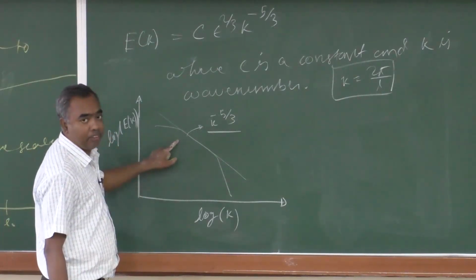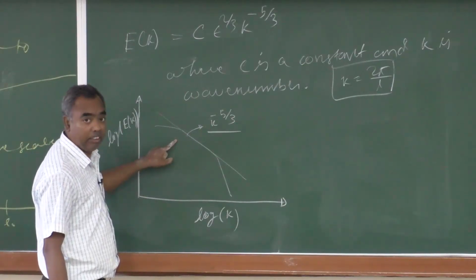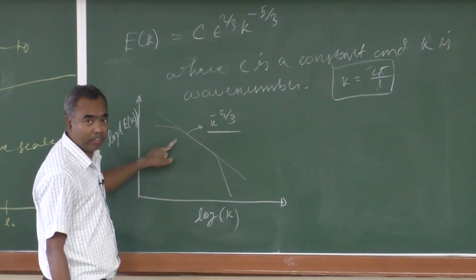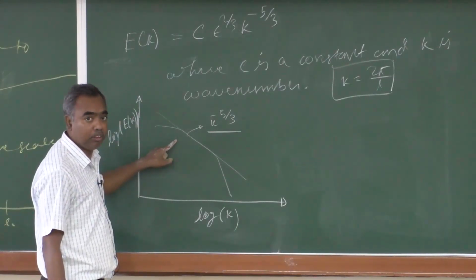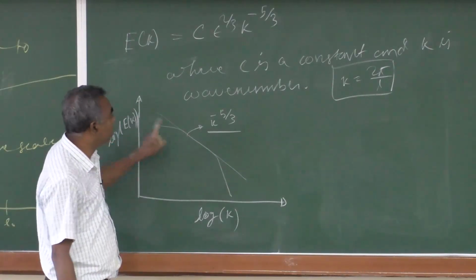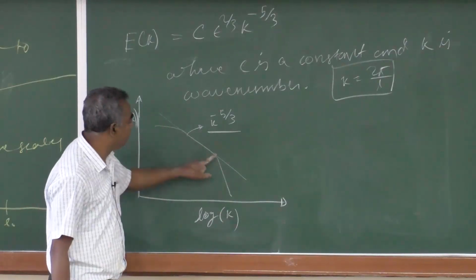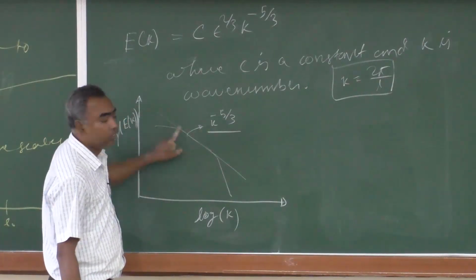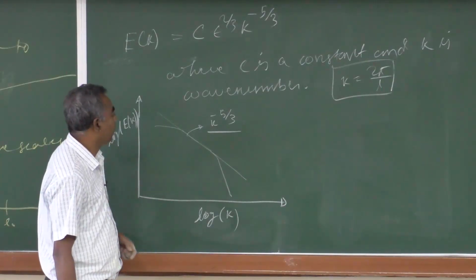So, in fact, you can check this with the data sent to you, okay, the measured data which is already shared with you, both hardware and the PIV measurement data in a turbulent boundary layer. You can use these data to find out this particular scaling aspect. You will see there is a small layer of minus 5/3 regime, okay.